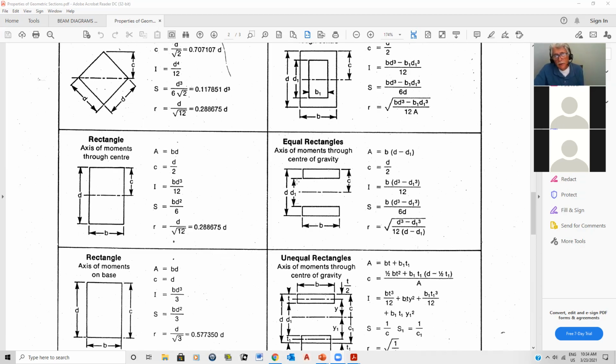And then after that, do I bother with these? Not necessarily. I use different ways, like the parallel axis theorem. I don't know if you guys remember what I mean by the parallel axis theorem, where I is equal to the moment of inertia with regard to the centroid plus the area times the distance squared from the centroid of each element to the central centroid. Okay?